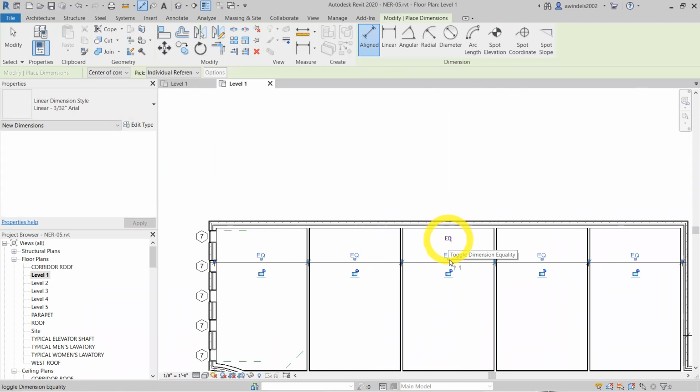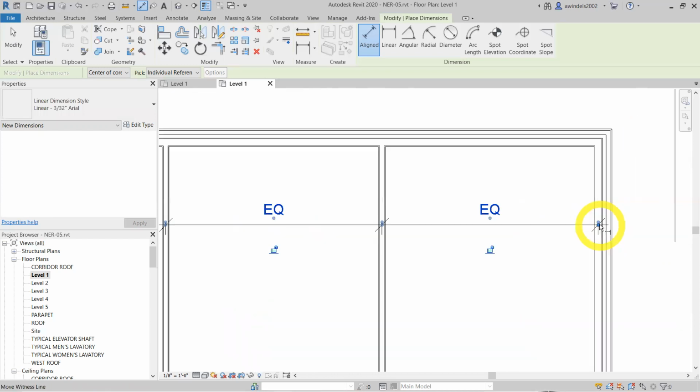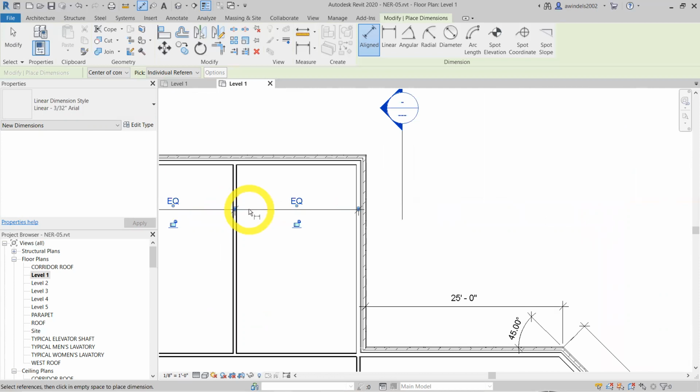Now, if I double click that, it equally placed each wall with respect to each other. So all 5 have the same interior distance with respect to the center core of the wall. So this spot or this spot in this interior wall. So that's what we did at the end of that page, which is a pretty cool command. Because these walls are always constrained to be equal, if one wall is moved, for example, all 5 partitions will always continue to maintain an equal relationship to one another.